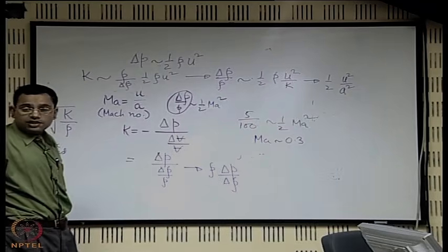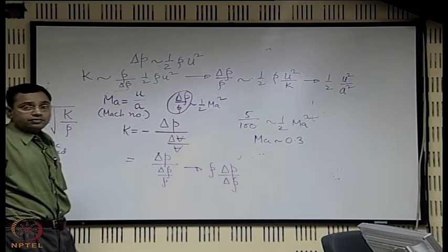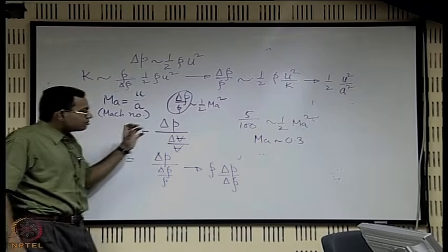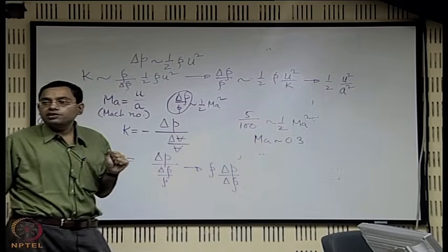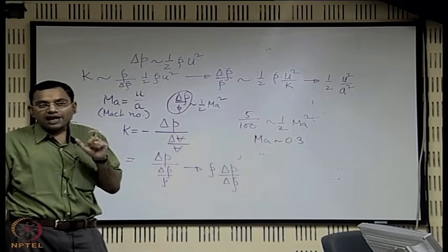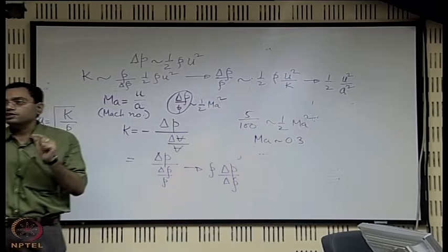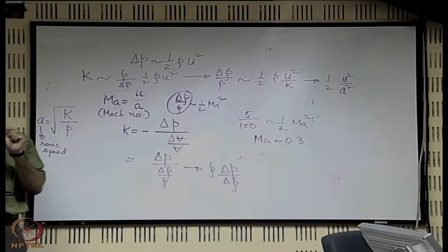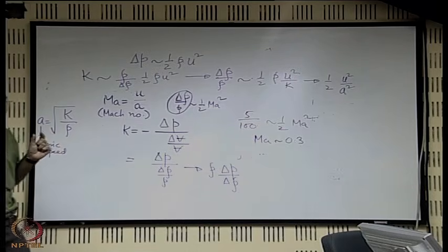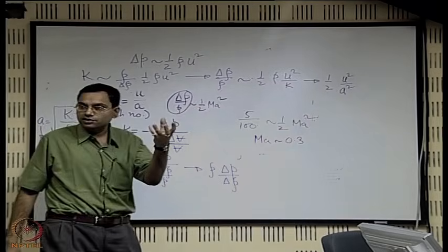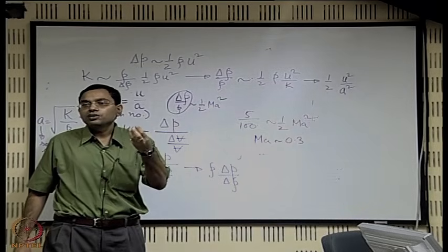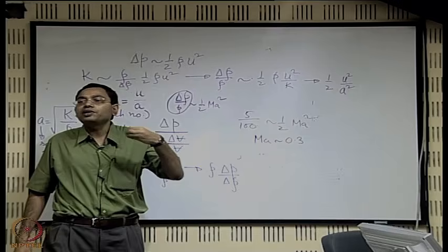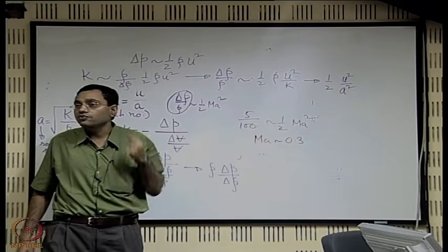The second important concept is as follows. Say you are interested to identify whether a flow is incompressible or not, and in that respect there is a subtle difference between the concept of incompressible fluid and incompressible flow. These are very subtle concepts. So when you talk about an incompressible flow, what you mean is that if you have a volume element of a fluid, that volume does not change.